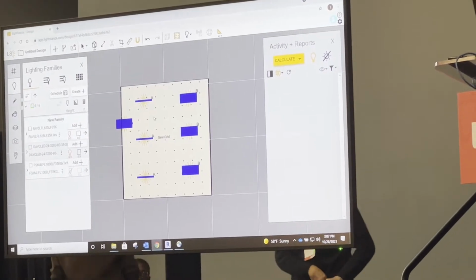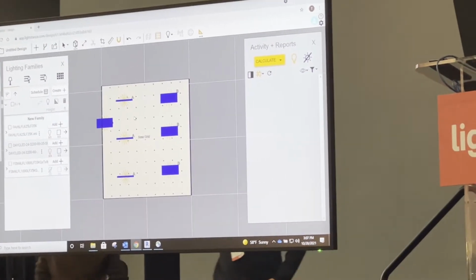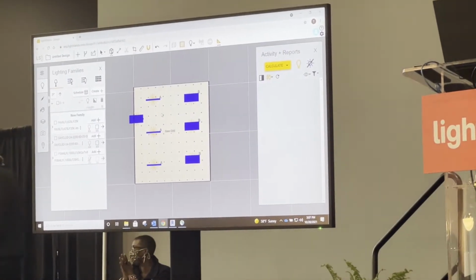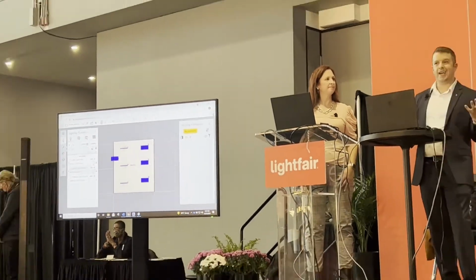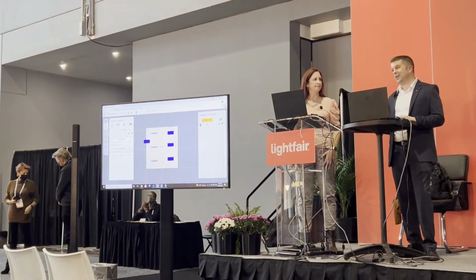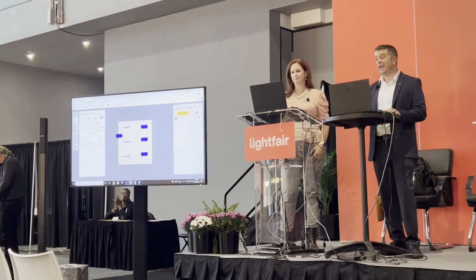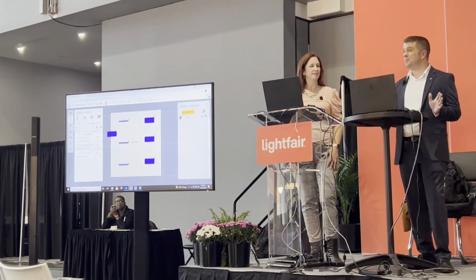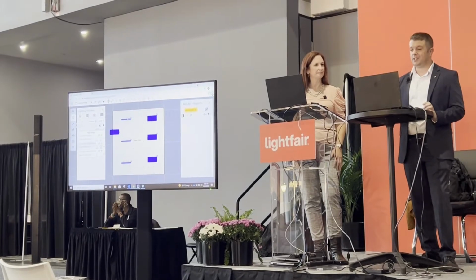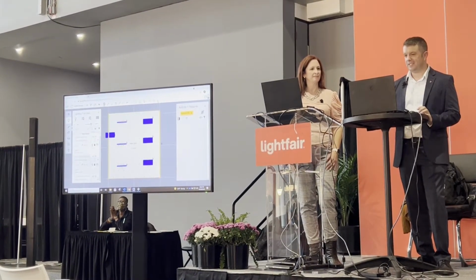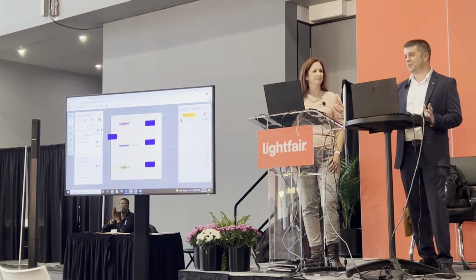Okay. Is there anybody here that cares about emergency lighting? Do we have any electrical engineers in here? Awesome, we got a few of you. Okay, so you know how traditionally you would have to create a normal lighting calc, then you would have to take that, create your emergency lighting calc. If one changed to the other, you've got to copy it over to the other one. Well, with LightStanza, you can do both in the same model. So what I'm going to do is I'm just going to pick a couple of these lights, not all of them. Say your emergency, pick you, say your emergency.